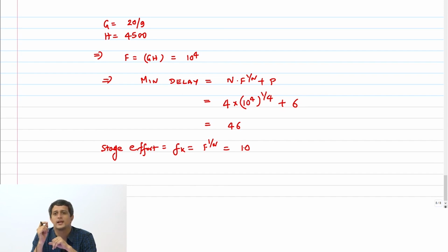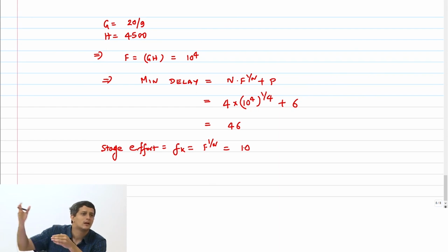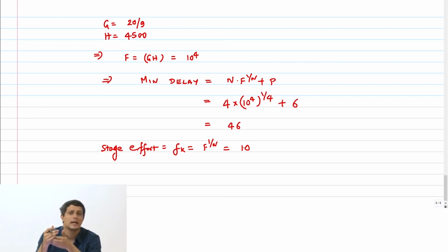Anything other than an inverter has an NMOS or a PMOS stack which is greater than 1, and therefore the logical effort is higher than 1, which implies that the delay will now only increase if I put any other gate other than inverters. By adding inverters on the path, I don't change the path logical effort. I can add any number of inverters.